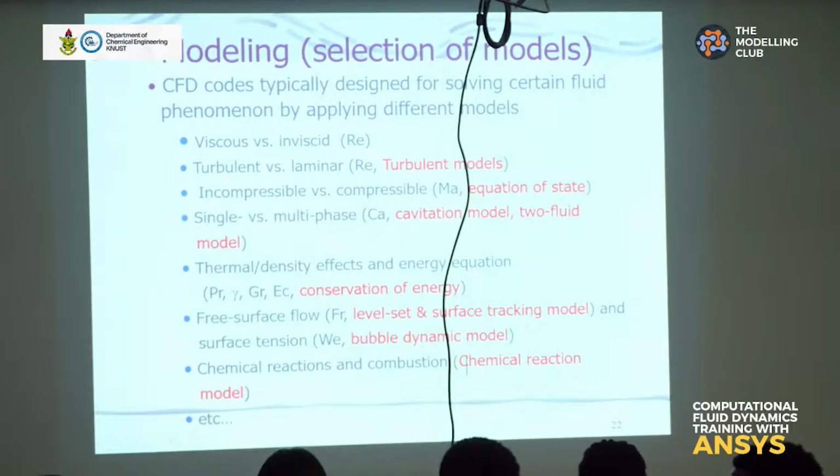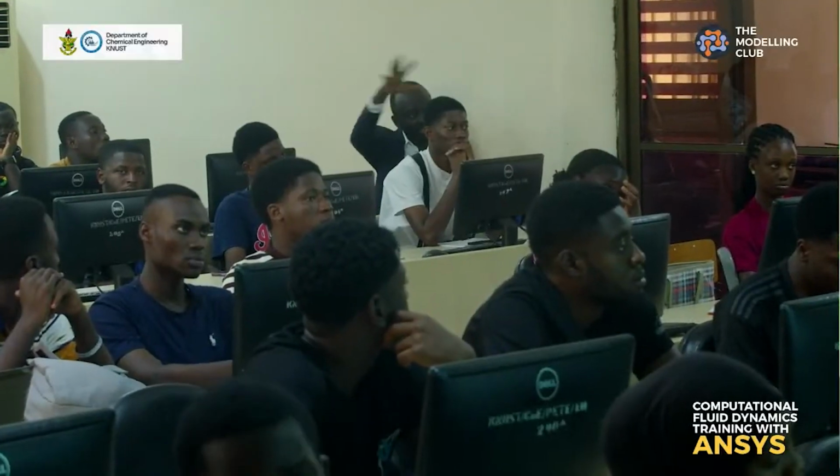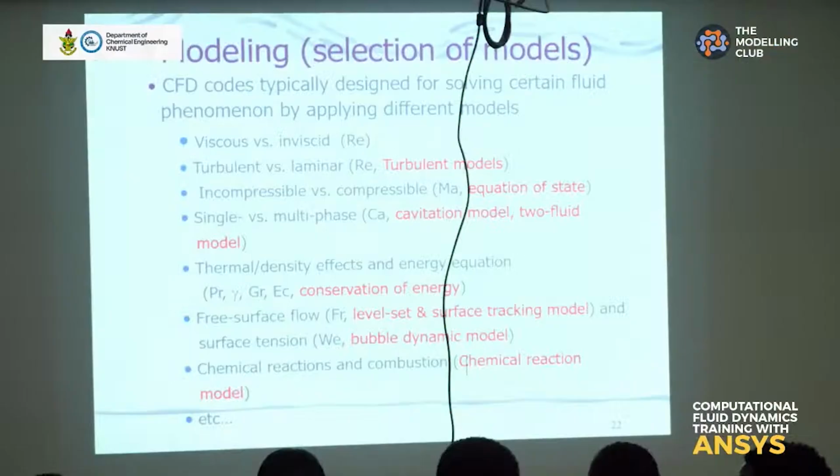According to some form of velocity distribution model, I wonder whether it is used to describe the velocity distribution. Yes, your turbulence model basically describes the velocity model. Some they call the large eddy simulation model. Some they call the Reynolds-averaged k-epsilon model, and so forth. So it's basically a way of describing how the velocity is distributed.